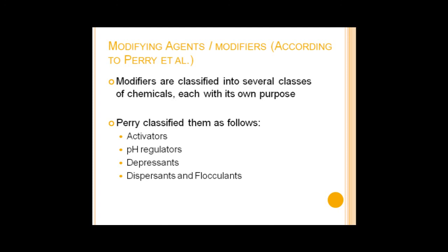Depressants assist in selectivity or stop unwanted minerals from floating. Typical are sodium or calcium cyanide to depress pyrite while floating galena.